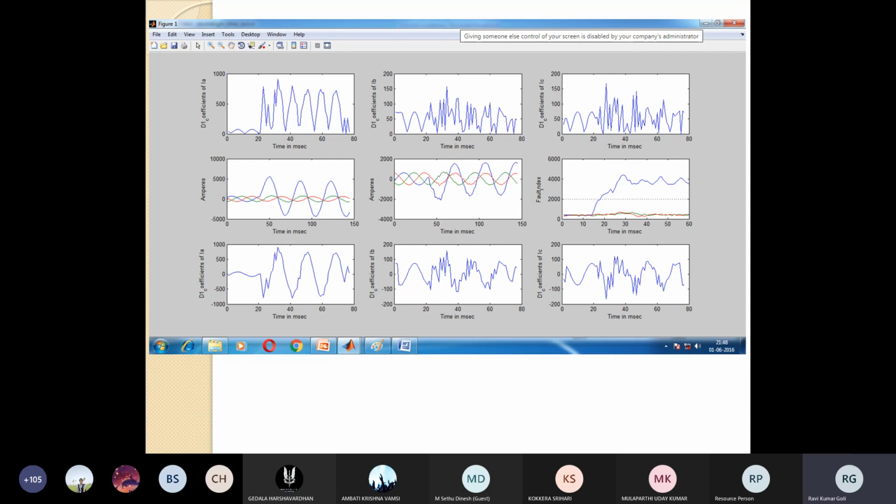And the original current signals also indicate that one waveform is a completely sine waveform, that is 5000 amperes, and the second one, negative is also there. Okay, here is 5000, the next one is 2000, and by comparing these two, the fault is nearer to bus 1.